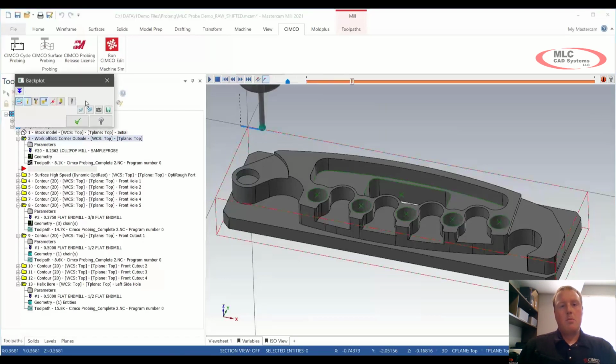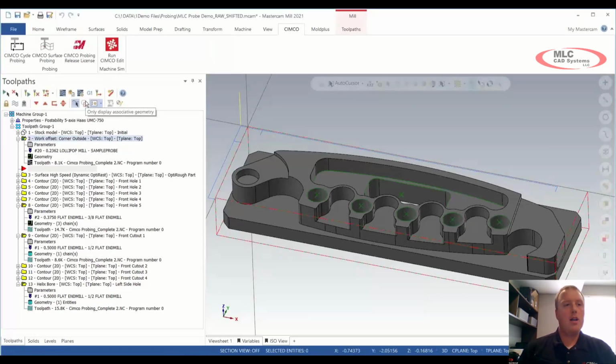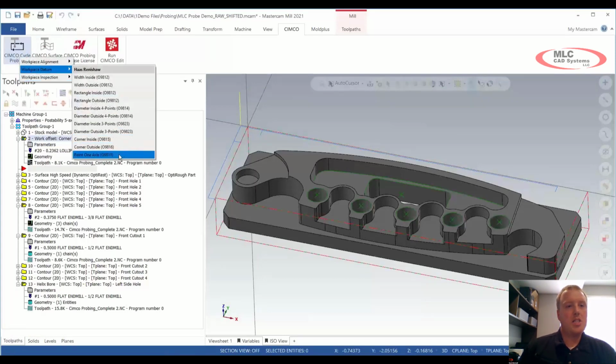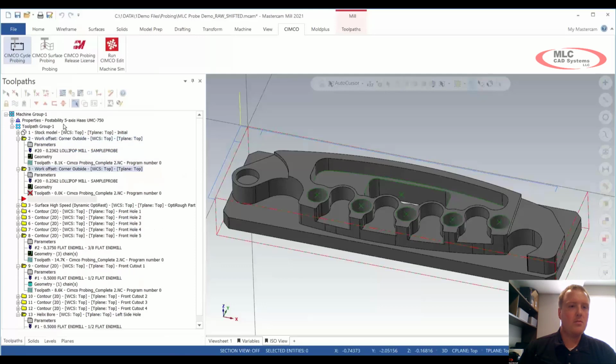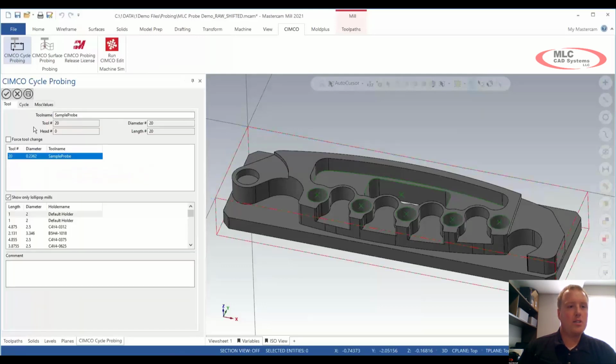Now for people that maybe don't want to touch on it and take 2 hits, maybe they wouldn't necessarily want to use the corner outside, and that's where then you could go ahead and use maybe like a 0.1 axis to do that. 0.1 axis allows you to just take, say, 1 hit on each side of the part as we'd like, and then set those axes as my 0 points.